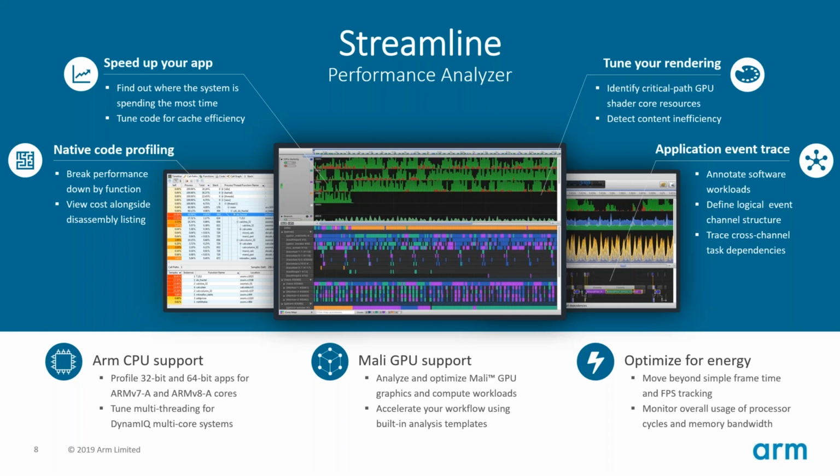You can do overall tuning, so you can see for an application, is it spending its time on the CPU? Is it spending time on the GPU? Within those processors, which of the functional units is the critical path? If for shading, is it arithmetic? Is it texturing? Is it memory access, for example?